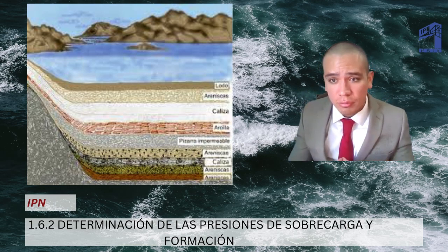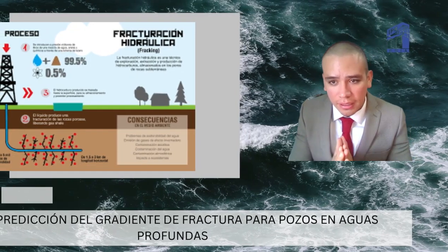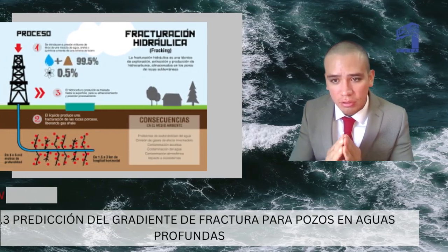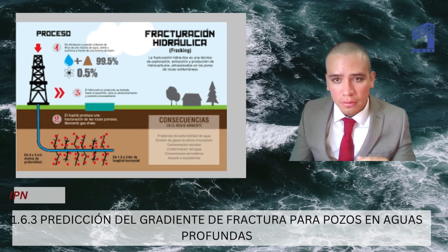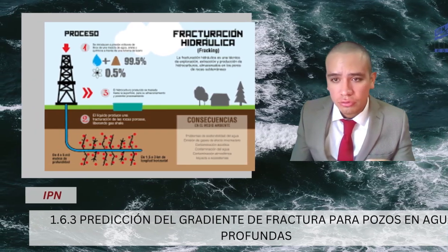Anchor holding force. The anchor is an important piece of equipment in a laid down marine system. There are correct and incorrect ways to operate an anchor. A well functioning anchor has its shank horizontally extending at the first design and predicted angle, and the anchor is designed in such a way that an increase in the horizontal force occurs and it will be buried even deeper.